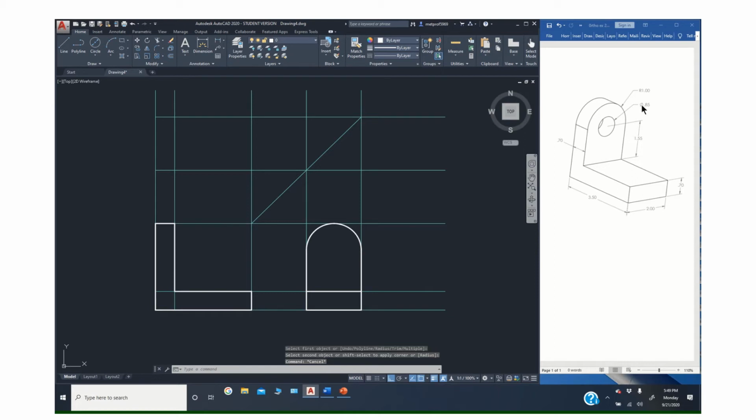Okay, and now I have that 0.85 diameter hole in there. So let's go to my circle tool. Now if I bring my cursor there, don't click on it. It'll identify the center point, and then I can just put in that value. So that's what my right side view looks like. Again, I see this surface here and this surface. I don't see that, just like I don't see the side when I'm looking at this view. I'm looking this way into the part.